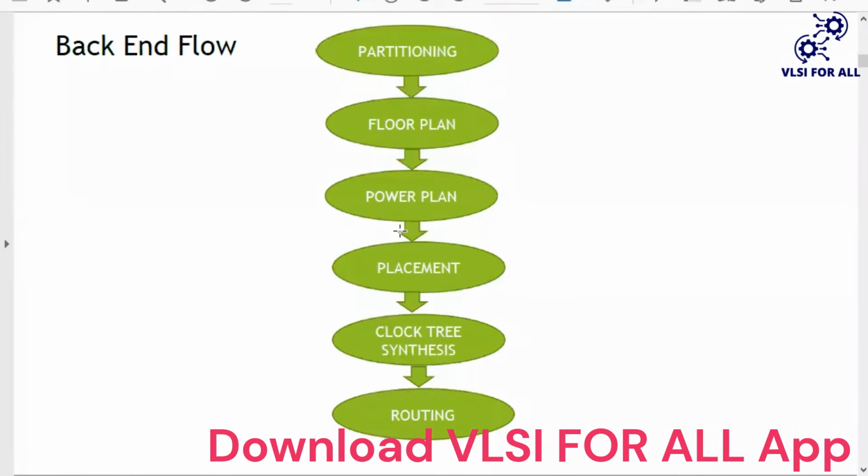Next one, clock tree synthesis. We know how it works with standard cells, combinational cells and sequential cells. In a sequential cell, there must be one clock input. Take the D flip-flop: D, clock, Q, Q bar. The clock needs to be connected and balanced, where the tool routes the clock at the CTS stage. In these two stages, placement and CTS, we can fix the timing violations.